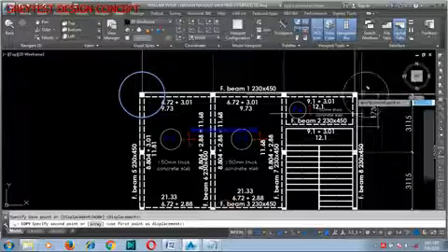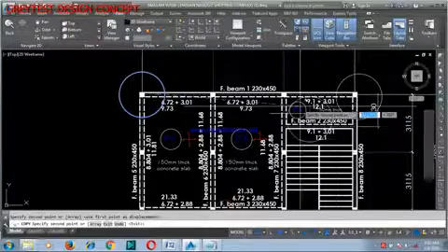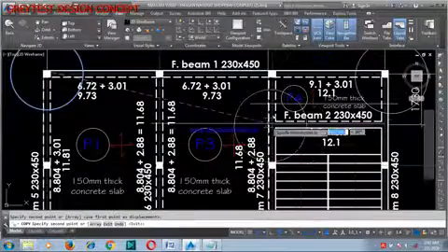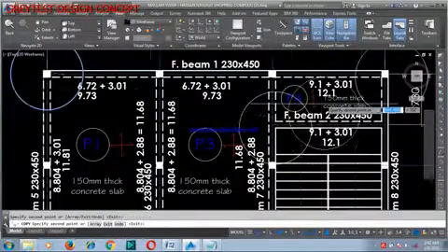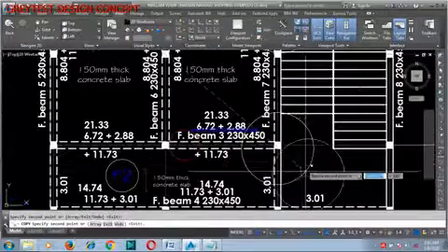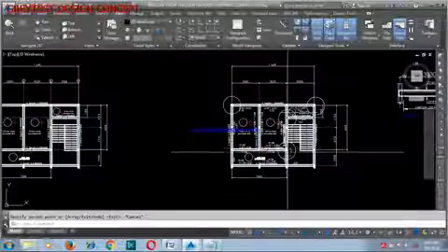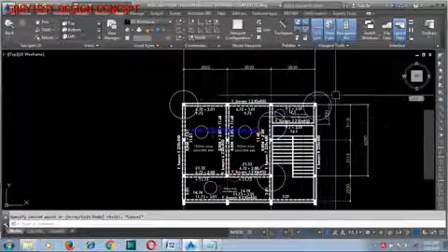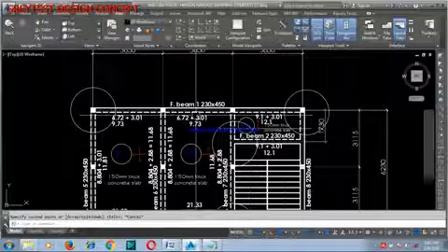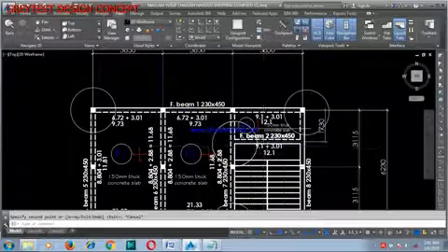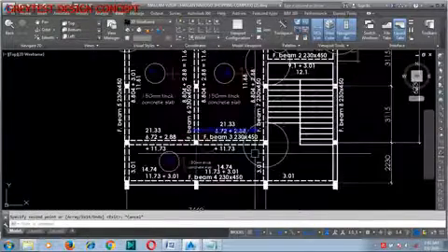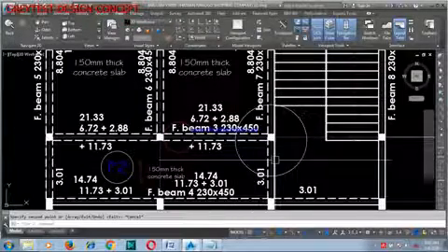What you get here is also an L shape. Okay, now check this out. On beam 2, what you see here is a T shape, right? Here too, what you see here is a T shape. Okay, now that is how to understand what an L beam is and a T beam is. So that means our beam 1 is actually an L beam, our beam 2 is actually a T beam. Okay, our beam 3 is also a T beam.